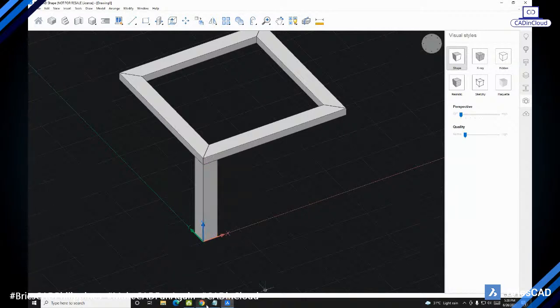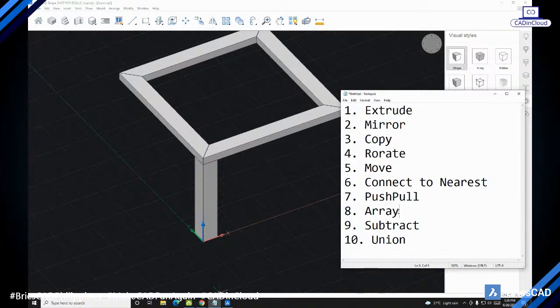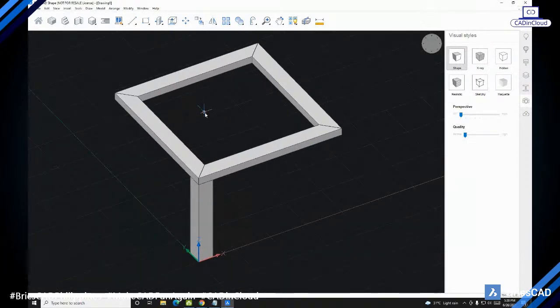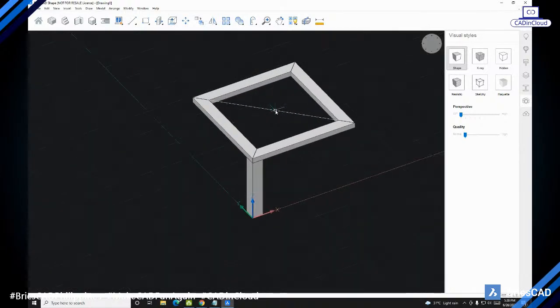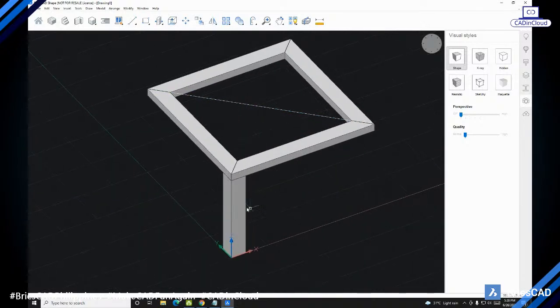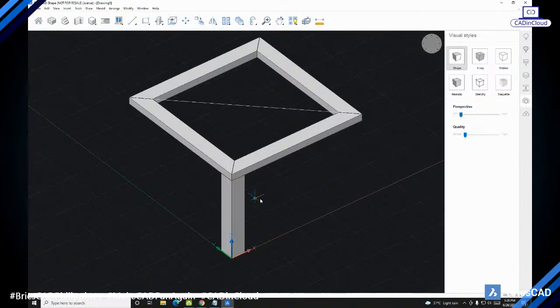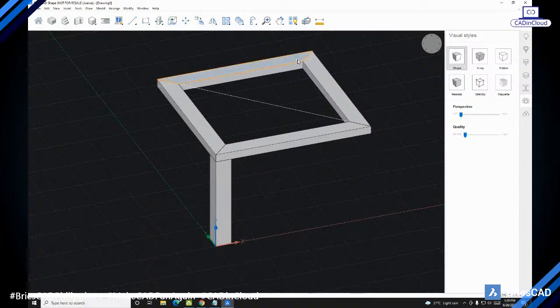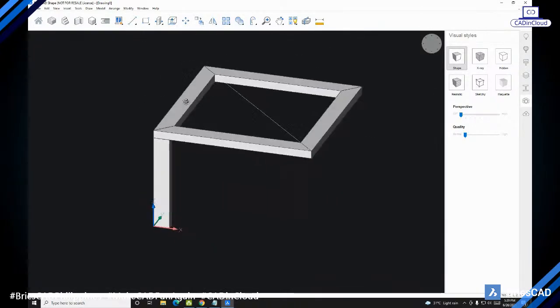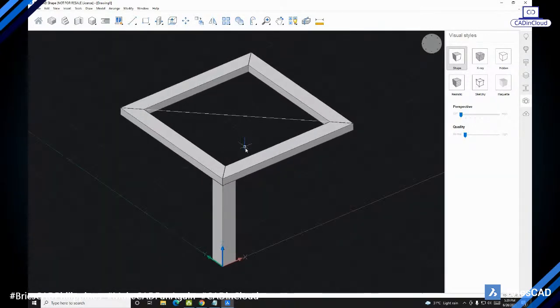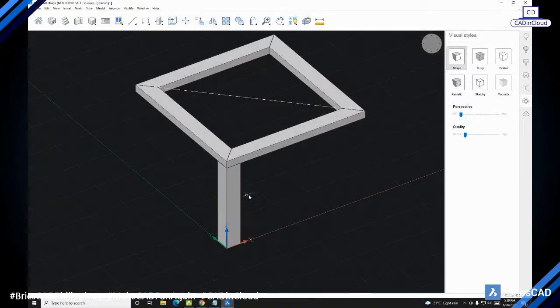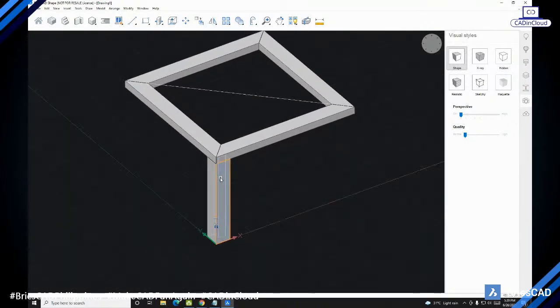After that, dito na natin isali yung first option ng array, which is polar. So we are going to use polar array. Hindi ako makagamit dito ng special snap sa BricsCAD shape, so we're going to create a line here as my reference. Kung nagmamadali ka para ma-create to, yung mga paa na to, pwede mo naman itong i-mirror if you want. You can do mirror, but kung nagmamadali ka, pwede namang array.